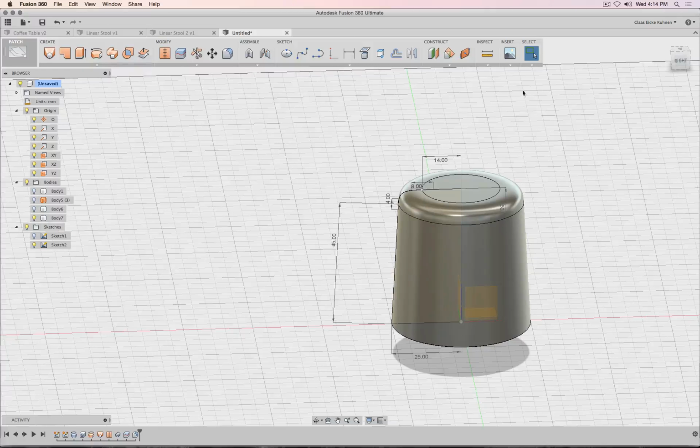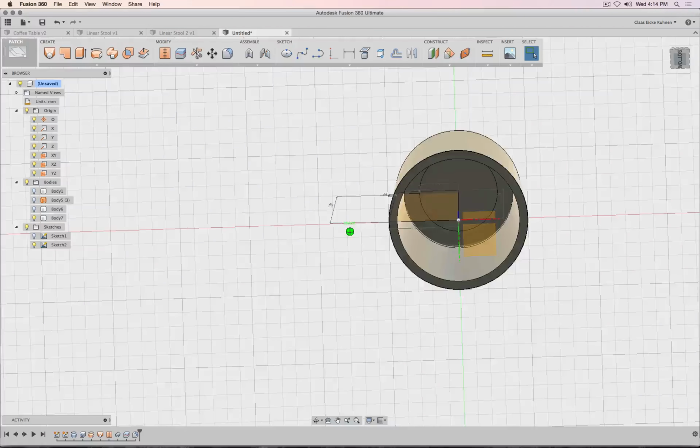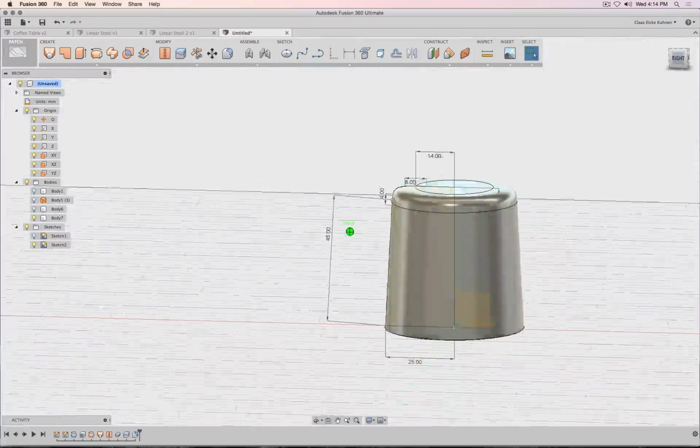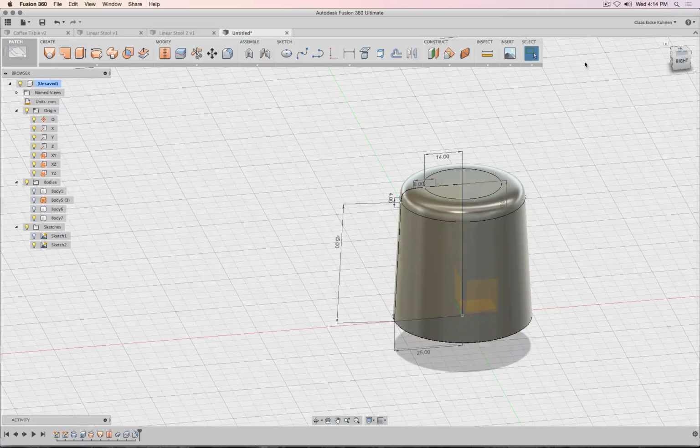Pretty nice. So which way you use is really up to you. They all have their ups and downs. Because we have the loft, actually I really like this approach because I have more control over how to blend the surfaces with the loft command. Or if I don't need that and I want to use the solid command, then I can have control over the transition by constraining the tangent spline, which we put between these two lines.